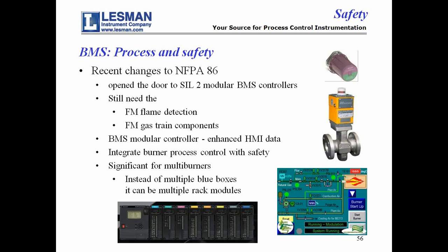The one out there that people talk about, well, do I need SIL 3 is the big question out there. And I can't tell you that. The vendor is not supposed to tell you what you need. You have to go through what they call a HAZOP, which is an analysis process in order to determine what level of SIL is required to reduce the risk to that which is acceptable.